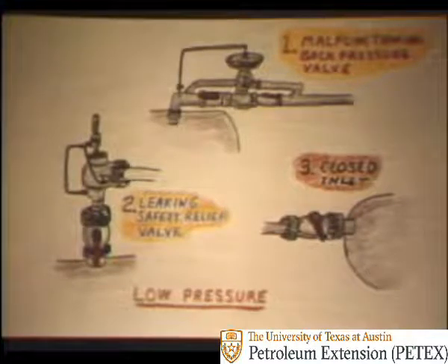The next problem we will look at is that of low pressure in the separator. This is usually caused by a malfunctioning back pressure control or a leaking safety relief valve, or possibly the inlet valve to the separator is closed.